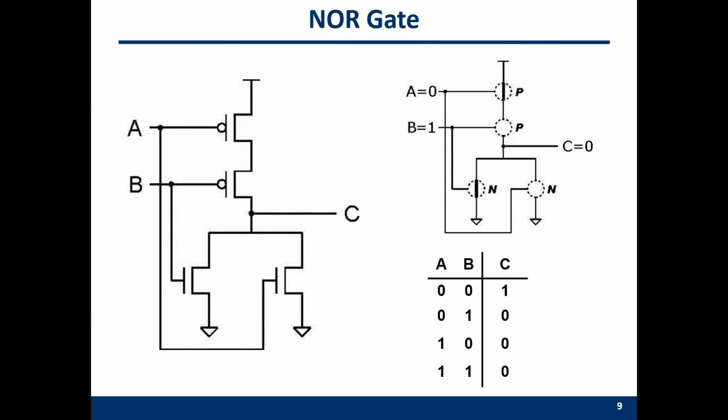And when we need to check A, then we need to look at these two gates. Since A is 0, this is open, and the upper one is closed. Because the two PMOS in the pull-up network are consecutively connected. If any of them is disconnected, is open, then the VDD cannot pass through. So VDD has no influence on the output here.